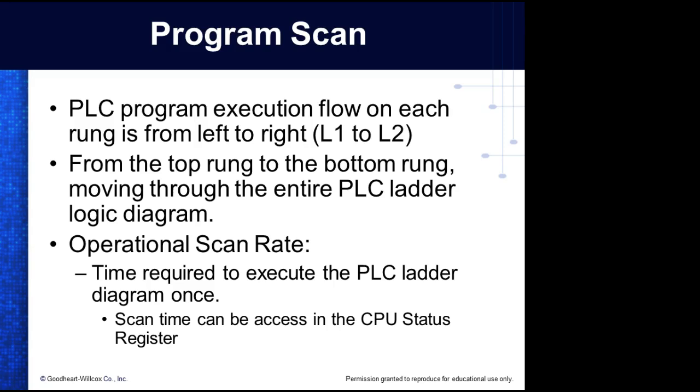And then they added things called interrupts that we'll talk about in PLC2, where you can make that push button generate what we call an interrupt, and it don't matter where it's in the scan cycle, it'll go out and take care of it. So that means we can take extremely important input devices and we can make it generate an interrupt.